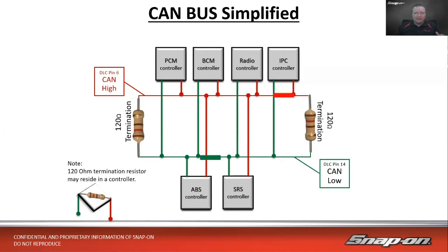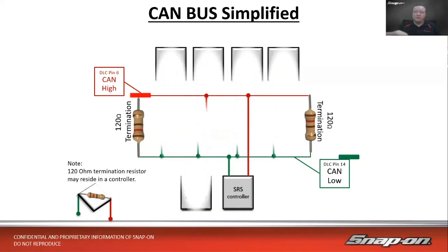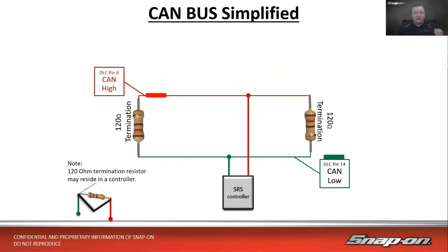I know on Subaru, we had a dealer installed shock sensor for the alarm. You would unplug the resistor, plug in the piece, and it just powers up, and there you go, off and running, talking on the CAN. You can even take the modules away and have just one module on there, and you could still communicate with it using the scan tool, right? It will still offer communication over that CAN bus, even if it's just one module on the bus. It'll still be transmitting information.